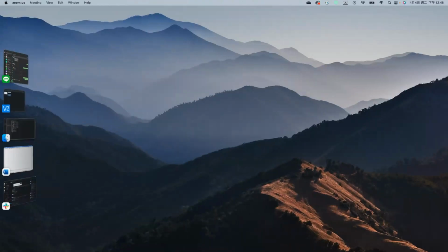Yeah, great work. It does point out that this is going to be an uphill battle to build trust in any of these tools, certainly as compared to the ones where the foundry is responsible for the rule deck that goes into them and commits to supporting an extraction deck in a particular tool. That generally requires a lot of silicon and a lot of calibration and testing to get it right. And I think you guys have the right approach in bootstrapping on the existing foundry decks and existing tools.